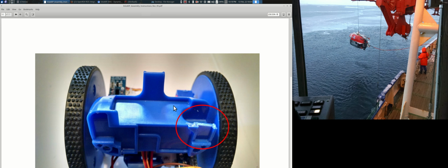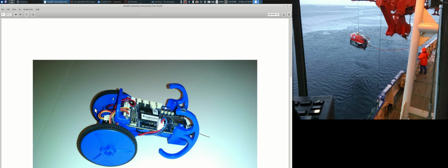The lower front bumper on the BeagleBone here, right here, it protects these wires, and it went between the boards on the old design where there was 2 boards. On this design where there's just 1 board, what we've done is we've drilled out the hole here, so this hole is now a clearance hole, and you use a half-inch number 4 self-threading screw to screw this in.